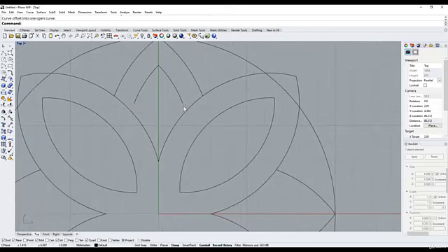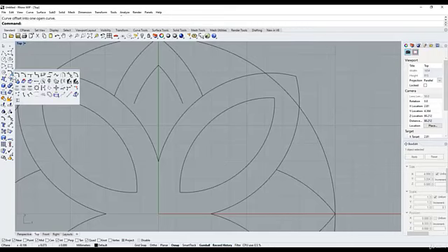And you can see that this one here doesn't quite extend to the edge here. We can fix that by coming over to this button here and cascading this out. This is our curve tools. And if we come down here to this button, we've got a couple of options to either extend curve if I left mouse click, or right mouse click gives us the option to extend a curve to a boundary.